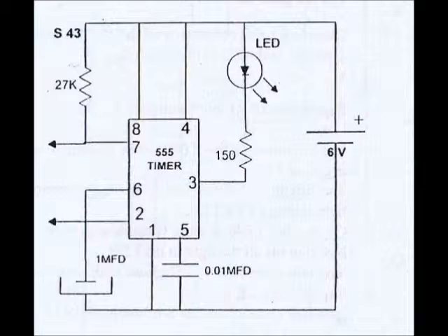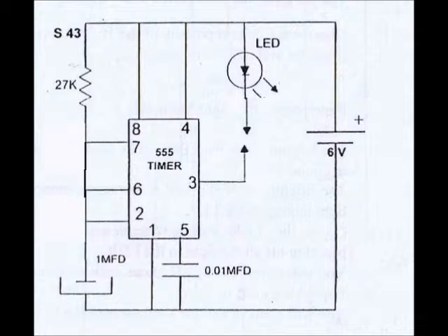Now we encountered some problems in creating our pressure tester circuit. Our chief problem was with the 150 ohm resistor. We speculated that this resistor may have provided too much resistance, thus not allowing the bulb to glow. To remedy this, we took out the 150 ohm resistor and replaced it with the two loose ends of the wires, thus using my body as the resistor. And this solved our problem for our pressure tester circuit.